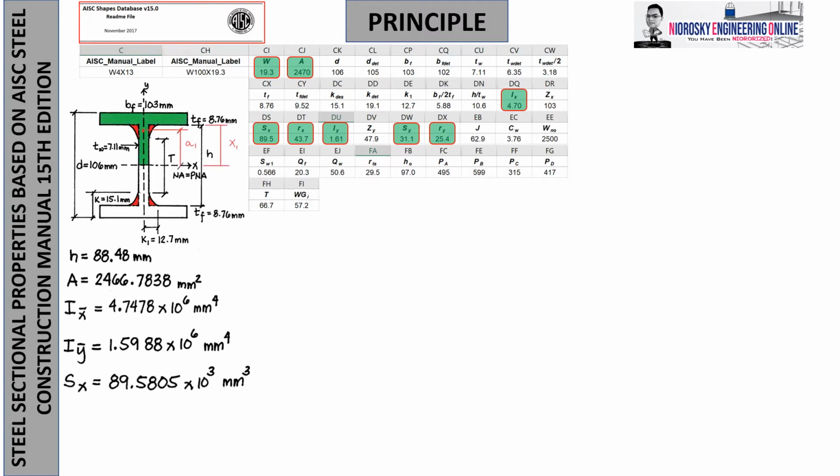Okay, so this time let's compute the plastic sectional modulus or Z sub X, considering on the stronger axis or in this statement that is the X axis. So notice that I have shaded the upper region by green. So, dyan tayo kukuha ng analysis since you'll notice that this is symmetric. So, therefore, what you can see at the bottom, let's say there's a value, let's say going to the axis, the plastic neutral axis as value of A2. And A2 equals A1 due to the fact that what you can see above is also the value below. Kasi symmetric. Okay, pantay sila. Ibig sabihin na makukumpute the value.